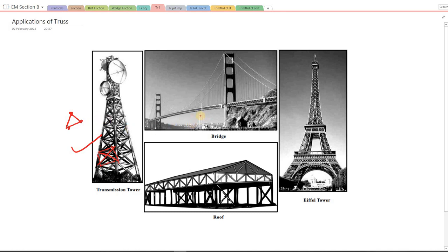Then the Howrah Bridge truss we saw is another application of truss. Then, as we were discussing, a roof structure is made up of truss most of the time. The roof decking is going to be made up of truss, and the roof covering is made up of, let's say, GI sheets. When we say a roof truss, or just roof, the roof has 2 components: roof deck and roof cover. Cover is the portion that blocks the rain or sunlight or whatever natural factors we want our structure to be protected from. Then the deck is the support system.